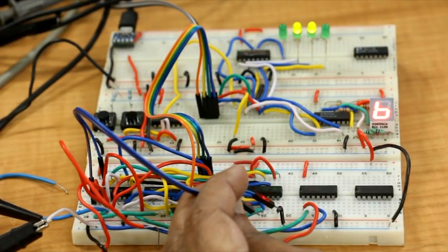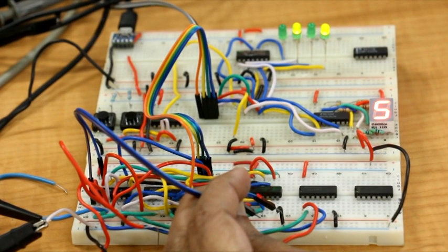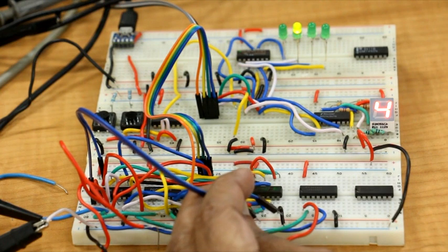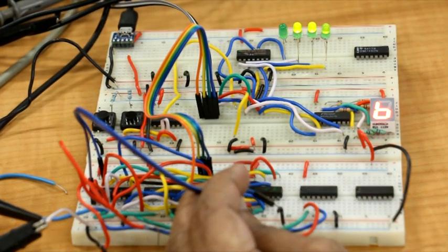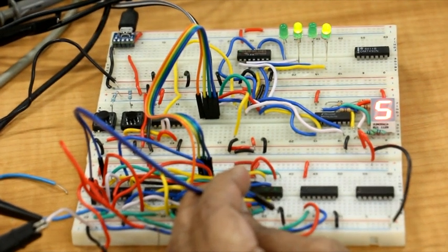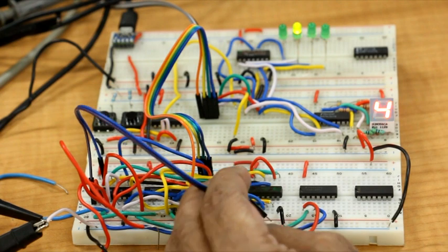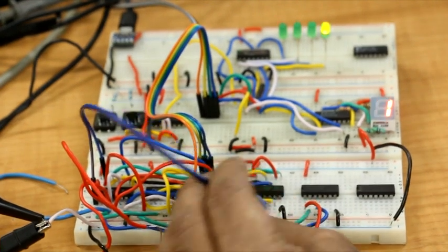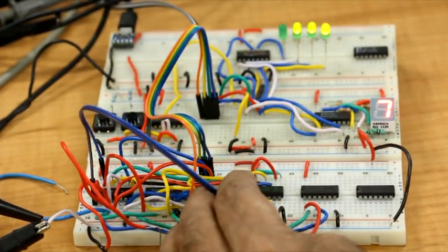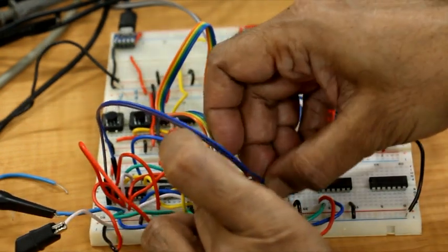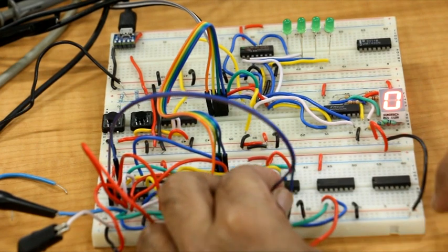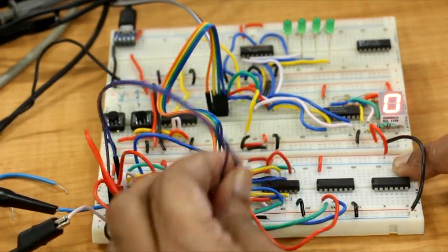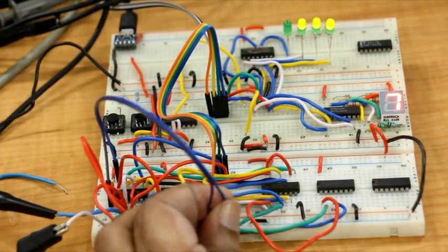I want to show you what will happen when an unused state occurs. Right now let me give you the case of all zeros, because what we have said is if it is all zero, the next state will be 7 or 111. Let's see it happening. Now what I am doing is I am clearing all the outputs together. Okay, output is cleared now. Let me remove it. You see that it just becomes 7.